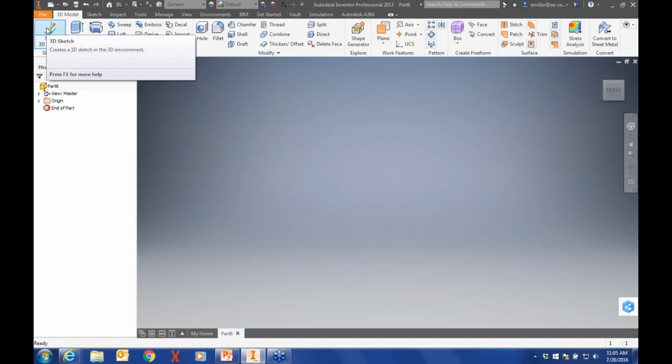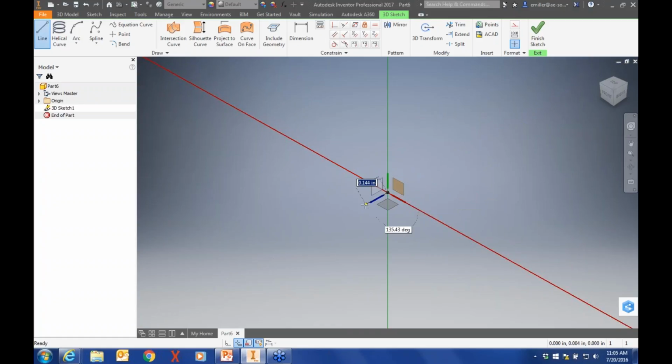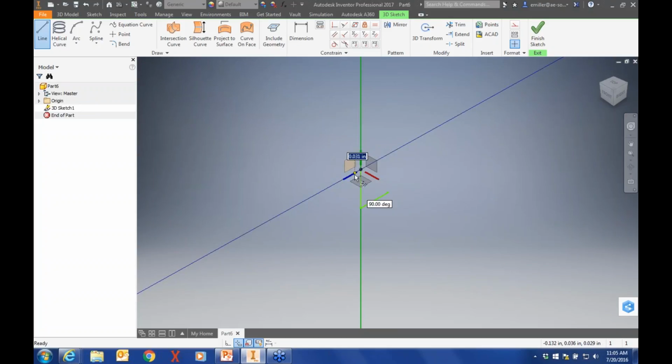I'm going to start a 3D sketch, and we're going to talk a little bit about that. We're not going to spend too much time on it, but if I start a line here, it starts me out in the 2D environment, so I'm going to go back to the home setting. If we start at the center, say I'm routing, this is just a straight line, but I can route along a specific edge, and then pick a different section and route along that. Notice my green line is where I was, and I'm building on that, and this little interface tags along as you go throughout your sketch.